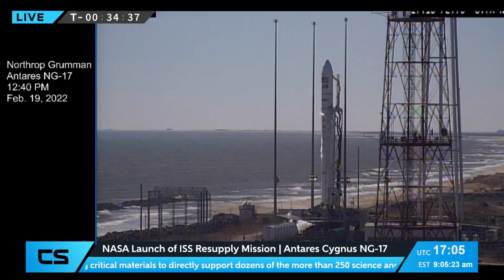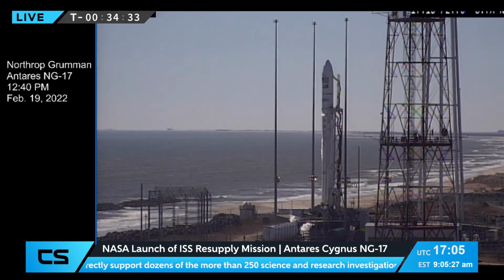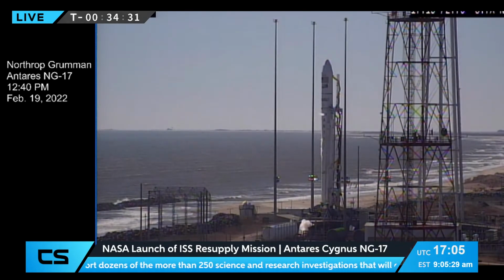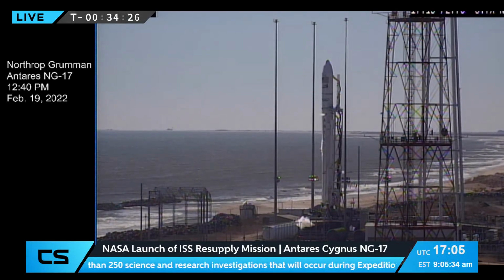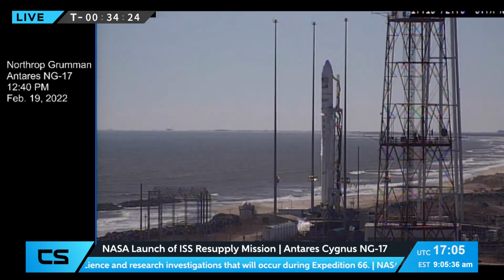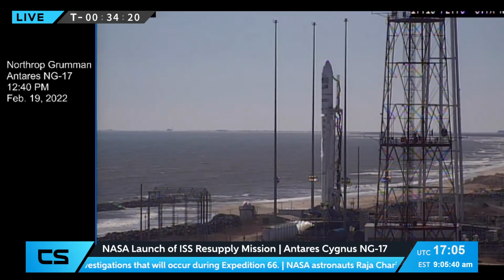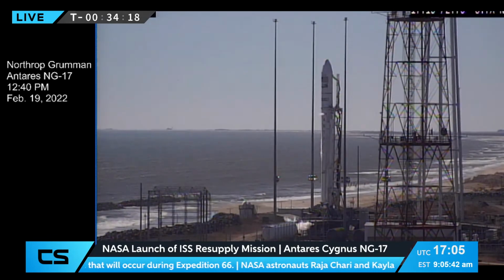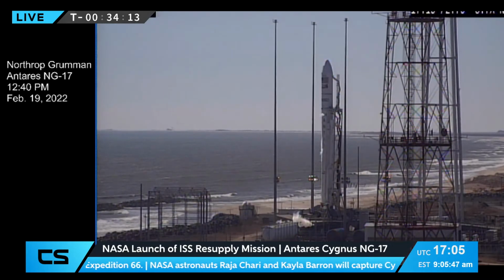Okay, launch team, we are passing through T-minus 35 minutes. Ops 1, step 360, you go to enable local launch enable button at the fail-safe panel and verify indicator illuminated. Launch enabled and illuminated. And GSO, enable your local launch enable button at the failsafe panel. Verify local indicator illuminated. GSO, launch enabled and illuminated.